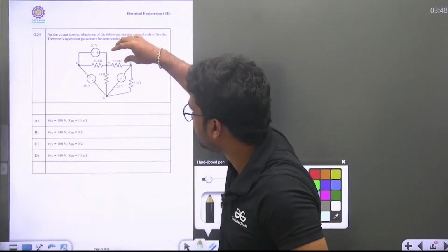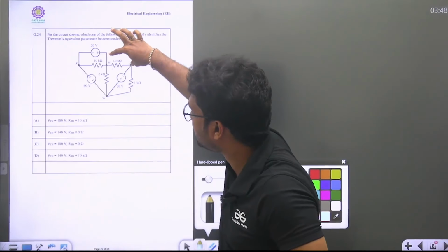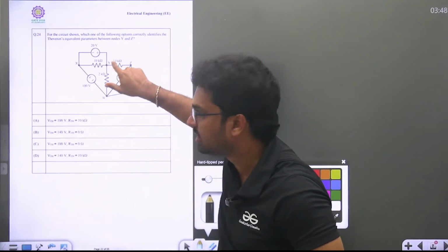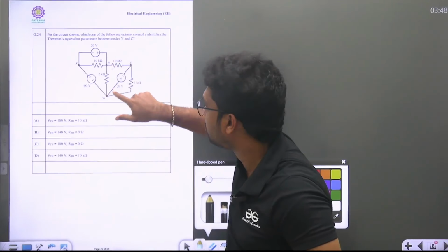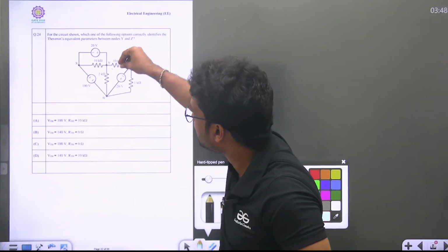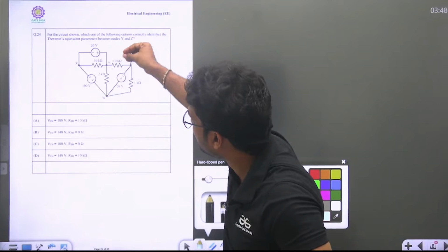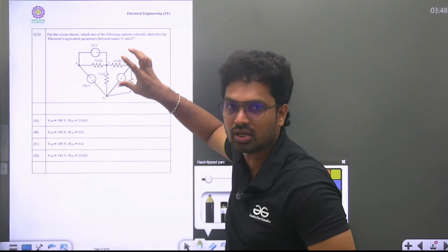But here we are finding, the examiner said Thevenin's between Y and Z, meaning maybe we may be connecting the load between Y and Z. In that case, you should not remove the resistor. If you need the response in this resistor, you may need to remove this resistor. But he has shown polarity inside, so maybe we need to remove it. It depends on the question, you understand.